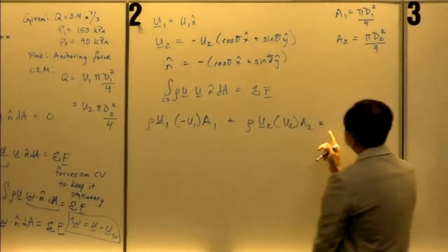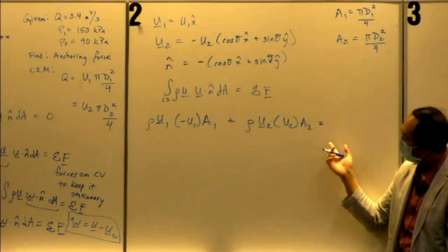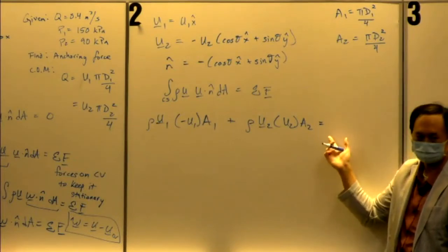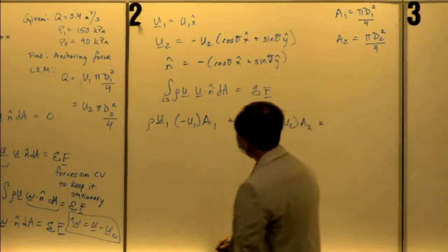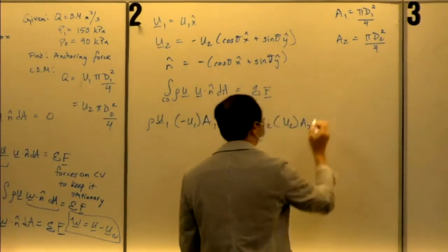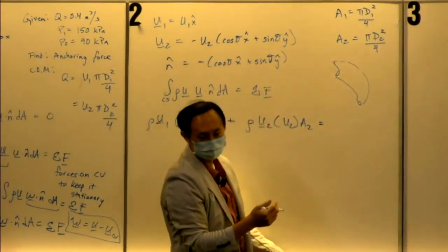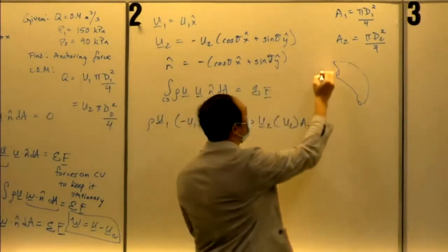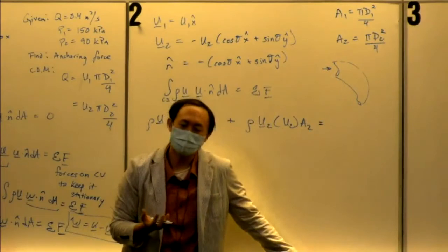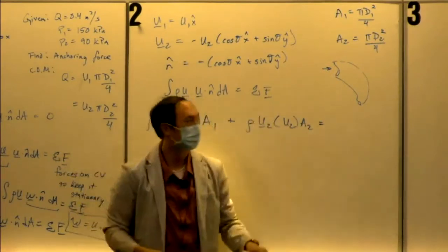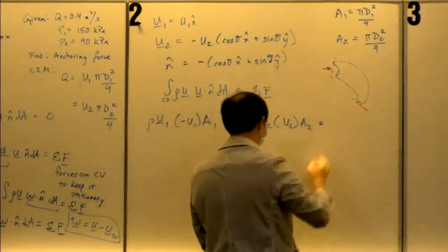Now, this is a pretty key part that I think some people on the quiz may forget because it seems like it's optional. You've got to include the pressures of the fluid because this is all enclosed inside the pipe. The direction of those pressures is always defined into the control volume, because that's what we call positive pressures. We don't like positive pressure because it's like crushing us. Remember from hydrostatics, we learned that pressure does not have a direction. It exerts equally in all directions. But once you've defined these two control surfaces, you do have a direction.